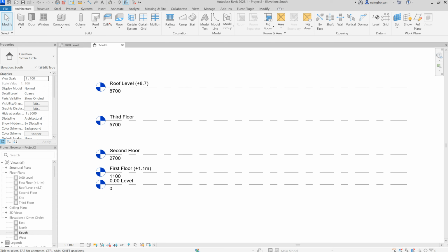So now we already settled the levels. Next step, we go to the layout plan. First thing, we go to 0, 0, and the levels will appear automatically. I will leave it between these 4 elevations to start the level. First, 1, 2, 3, 4 is vertical. So 1 to 2 is 3.4. 2 to 3 is 2.4 plus 3, so 5.4.